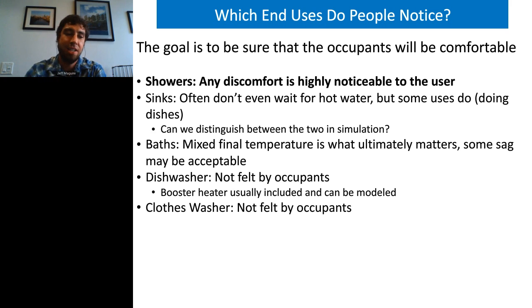For baths, you do definitely feel the water temperature, but a lot of bath draws are really energy draws, where what really matters is the final temperature of the bath. So if you want your bath to be at 110 and you start drawing at 115 and the temperature sags during the draw and gets down to 90 right at the very end, if your bath is still the temperature you want, that's probably fine. That would generally be acceptable to the user based on how you actually use hot water.